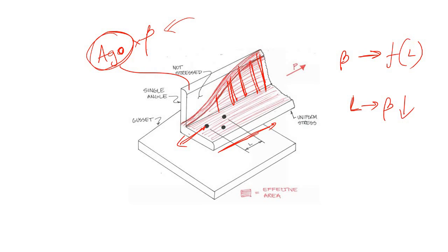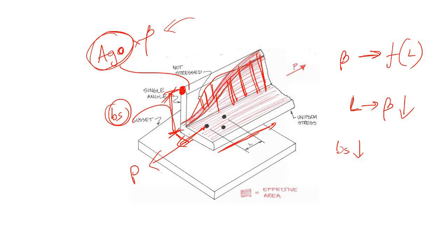Well, not only that, once we reduce this shear width, which is known as shear width, Bs, the distance from the farthest point which is not stressed to the nearest point where load is being applied, then also the stress development becomes quicker, which was the case of the weld connection. So once Bs is reduced, the shear lag effect decreases. So beta is a function of the length of connection Lc and this shear width, that is Bs.